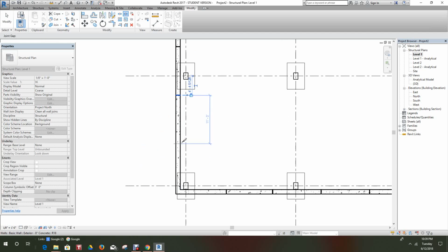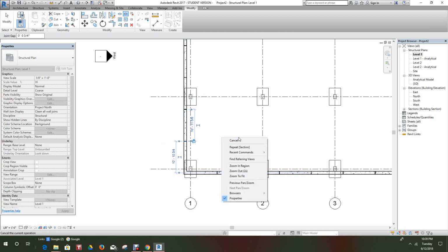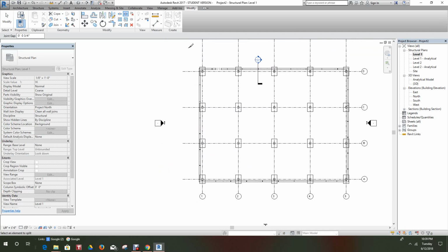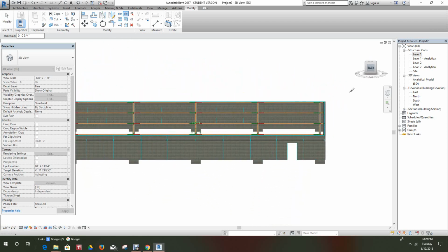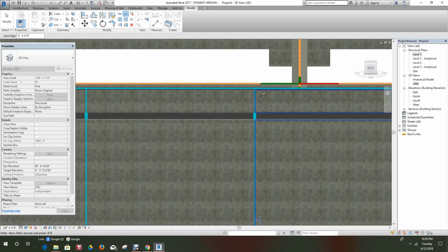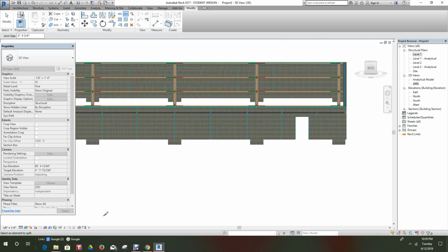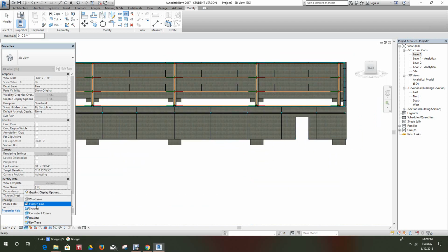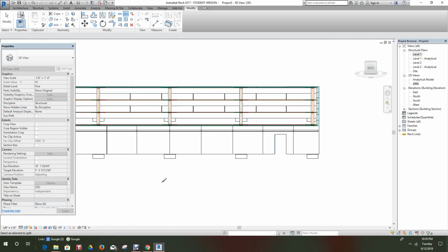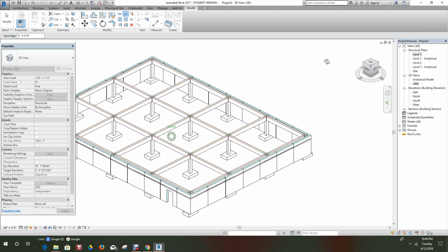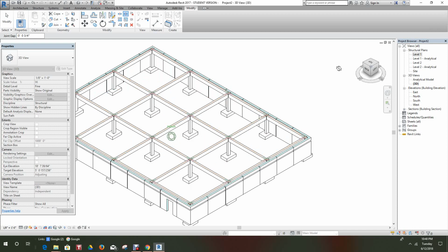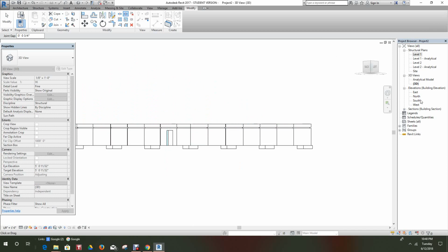types of ways. You can also use mullions, but I didn't have that much success with those. And then you can go here, look at this in 3D view, and there we have our wall panels, precast wall panels with reveals. Let's go in here and look at this in hidden line. So there you go. And also now, these panels can be adjusted.